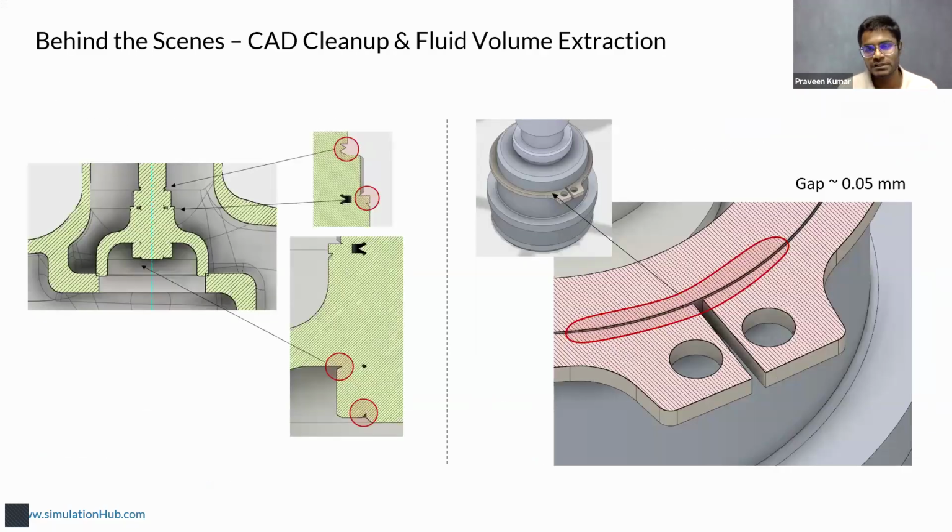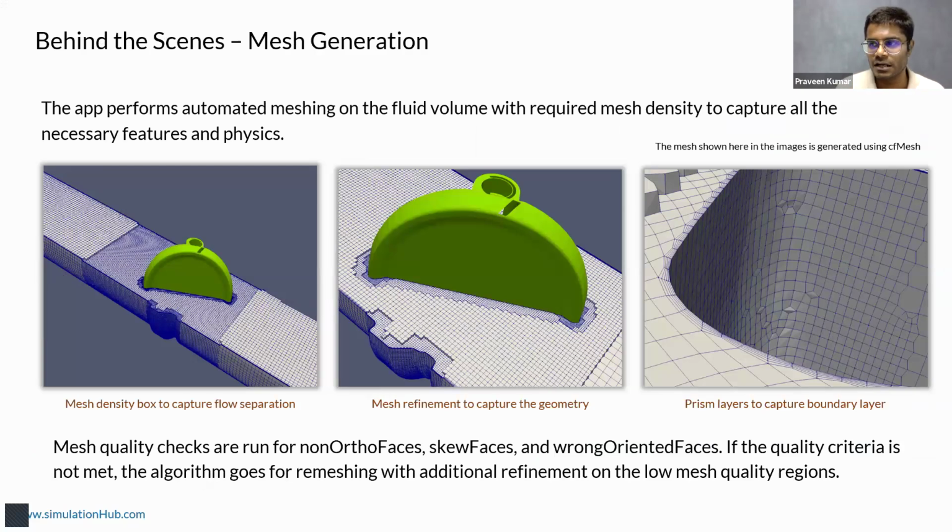What happens is the algorithm considers two parameters: one is the geometrical gradient, and the other is the flow-related refinement. It does both things, so it's not a uniform mesh. It's a proper CFD mesh, as if an experienced CFD engineer would do a grid independent study, completely with prism layers and everything.